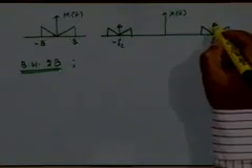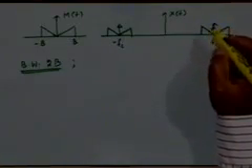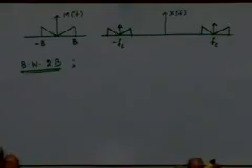So therefore, in that sense, this spectral component that we are transmitting is actually a waste of power, right, from that point of view. And therefore, there is a kind of power inefficiency that we have introduced by introducing the carrier component in the transmission process. So why should we do that?